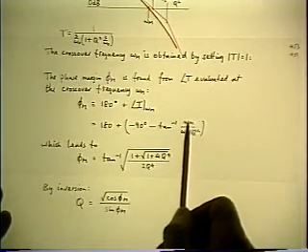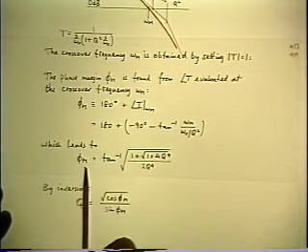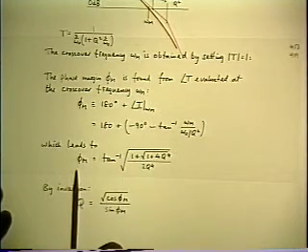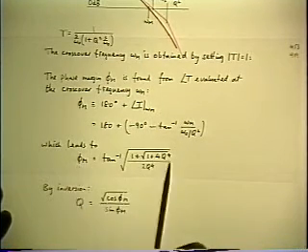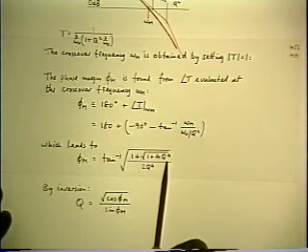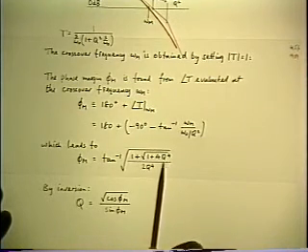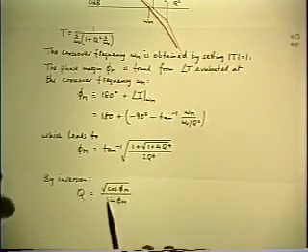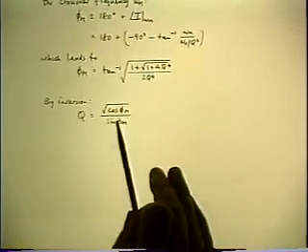And when we substitute for the omega m that we just solved for, you get this. So this is the relationship between phase margin and the peaking factor of your closed loop gain. And you can invert that expression and get this one. And that's the bottom line.